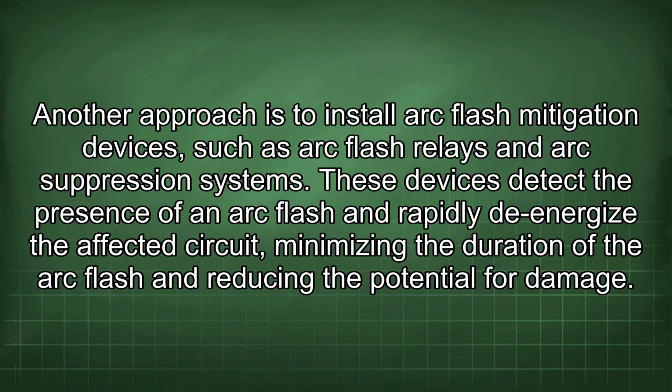Another approach is to install arc flash mitigation devices such as arc flash relays and arc suppression systems. These devices detect the presence of an arc flash and rapidly de-energize the affected circuit, minimizing the duration of the arc flash and reducing the potential for damage.